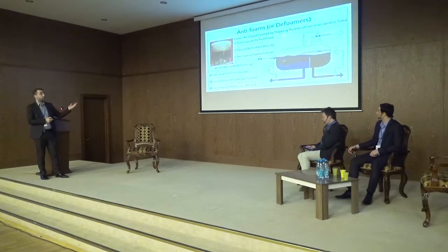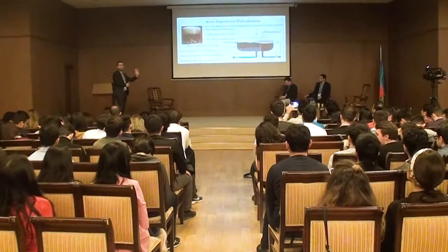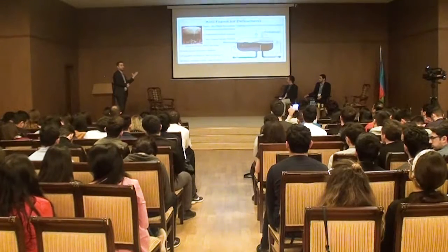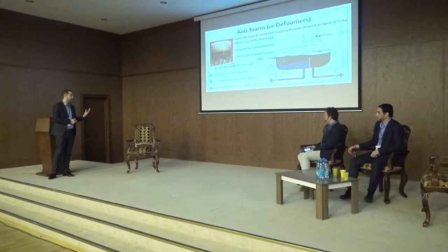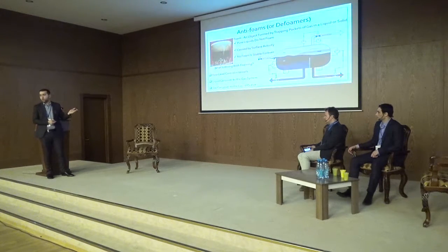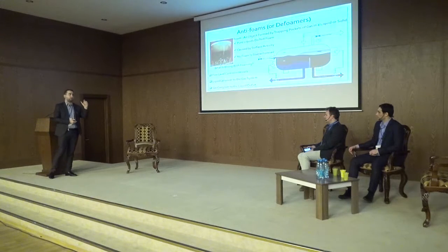First of all, I need to note that pure liquids do not foam. If you have only water, it doesn't foam. You need to have some surface active components in it to have foaming, and it's caused by surface activity. And no foam is stable forever. No matter how foamy your liquid is, if you leave it for a few hours, it will go. The foam will collapse. But unfortunately, we don't have that long a duration in our system. We only have a few seconds to collapse this foam, which is why we need antifoam chemicals.